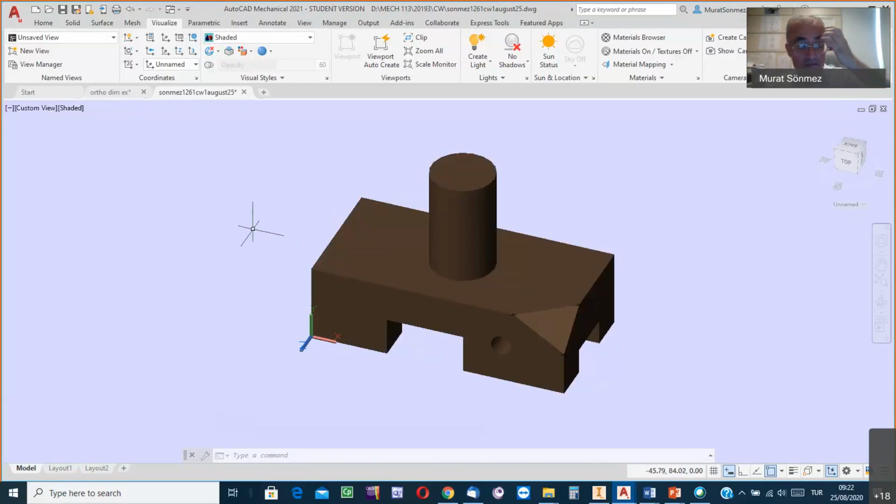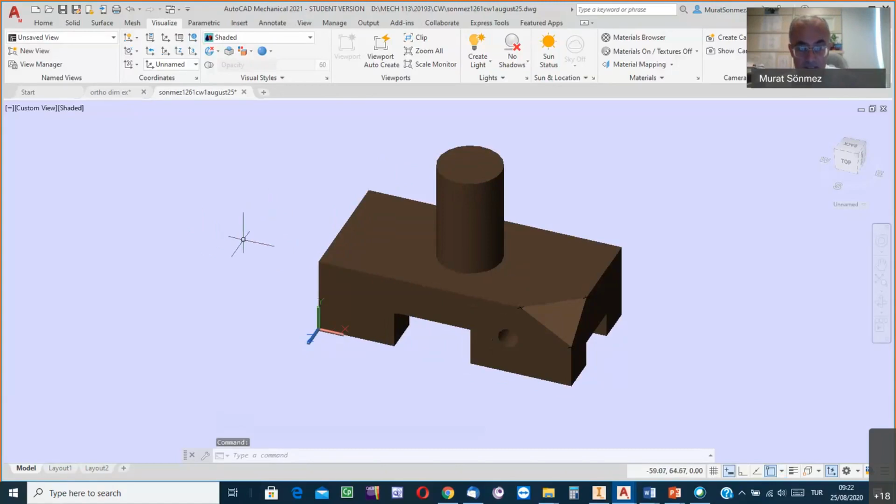What is that? See my demonstration. By the way, whenever you need the XY plane not coincided with a certain surface but with another surface, while the origin is suitable for you, there is no need to change the origin, just change the plane with which the XY plane coincides. Then, you know, rotate the coordinate frame.